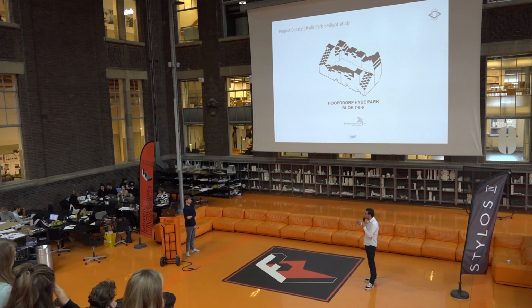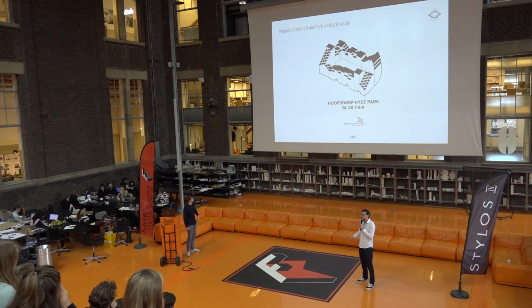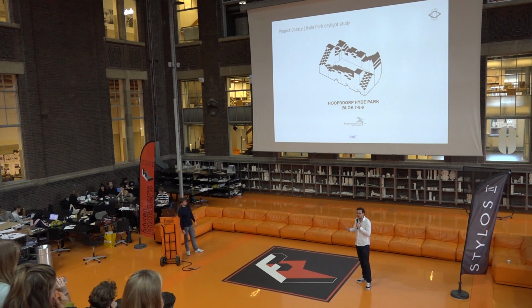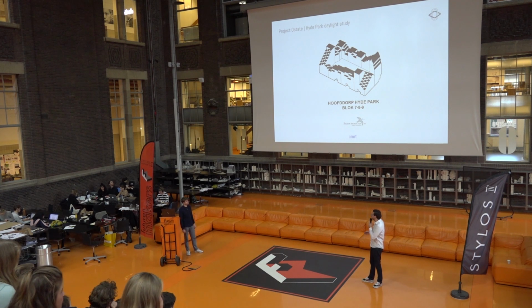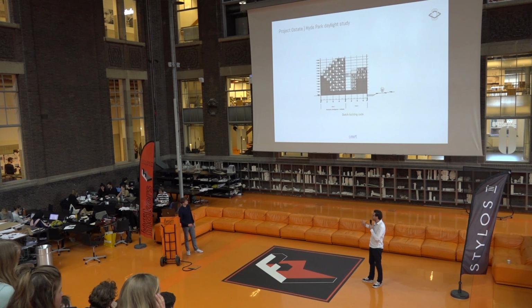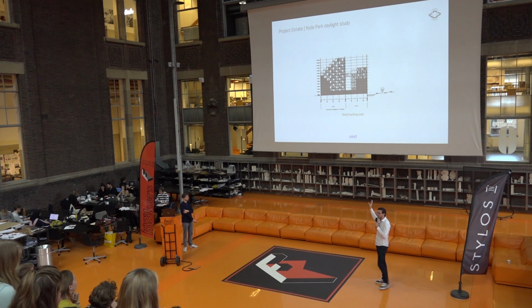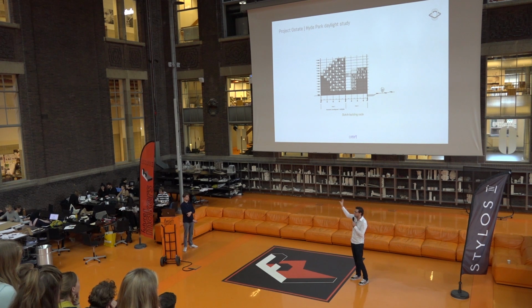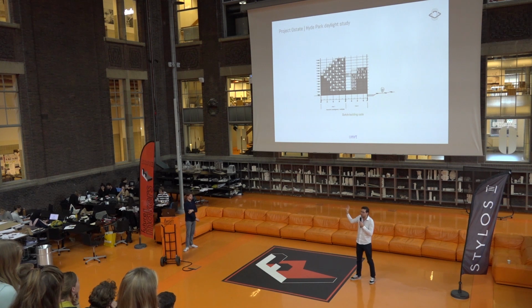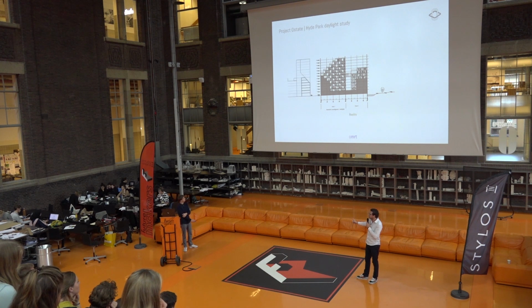They wanted us to do the calculations by the normal building code regulations of daylight, because they were afraid about how much daylight would come in. According to the building code, you can calculate a single house like this without the adjacent building next to it, while in reality this is the next-door building.